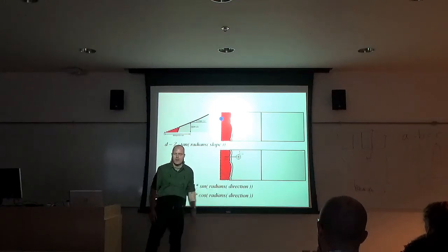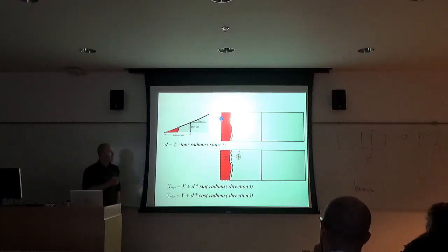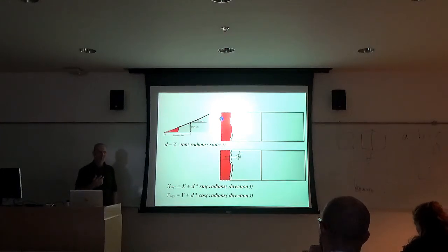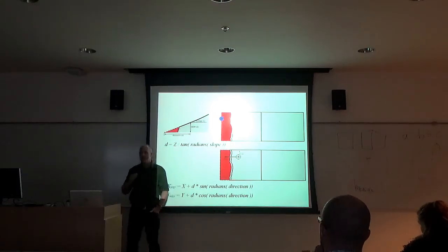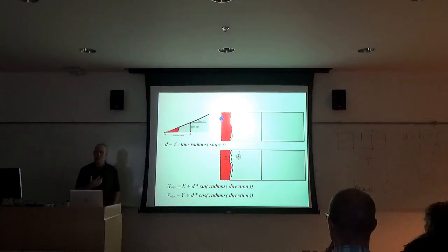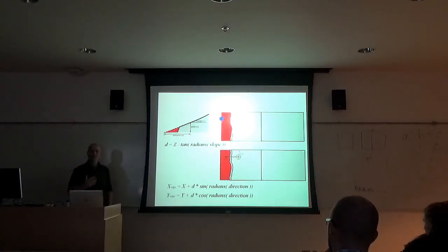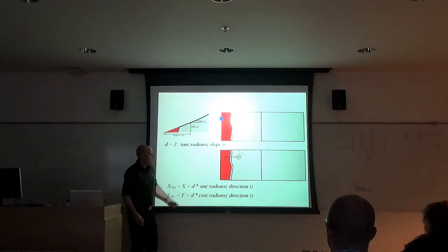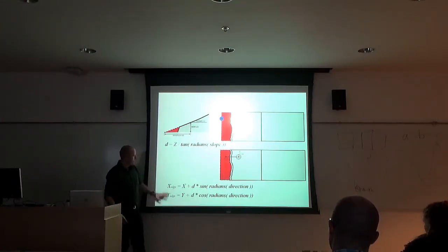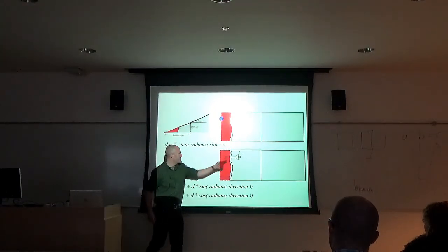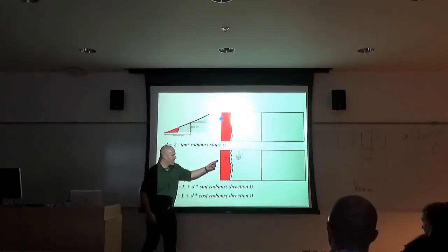And the tools I was using were, first I was using aspect, as this slide still reflects, and then I'm actually using distance direction in a distance matrix. So, first I used direction, then I used aspect. Because aspect, if you're thinking of, say, a terrain type thing, tells you what direction a slope is facing in. And that's exactly what we need here. And so I can use that aspect to figure out what the slope direction is, and then I can tell QGIS to use this coordinate and draw a line using that direction we got and stick a point there.